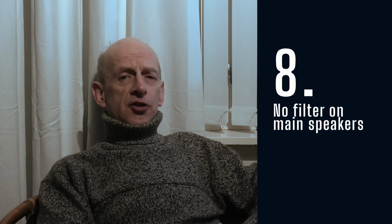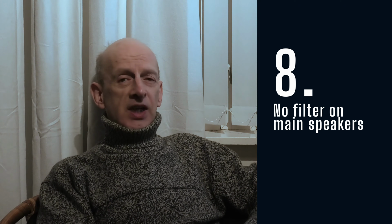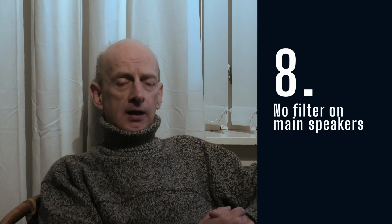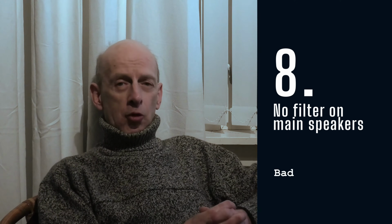Number 8 is no high-pass filter on the main speakers, thinking that our main speaker rolls off, and if it doesn't, it blends in with the subwoofers.